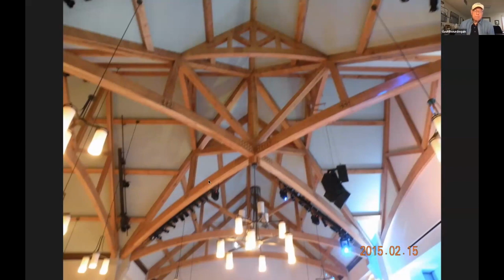Well, if you look in the back of the NDS, the most important thing is the layup. And for example, if it's a flexural member, you want the best fibers in the bottom of the glulam, and so if you look in the NDS, you'll see that flexural members have different load combinations than axial tension members. For example, axial tension members like this one, the lamination quality is balanced and symmetrical around the center line. So that's one thing to learn.